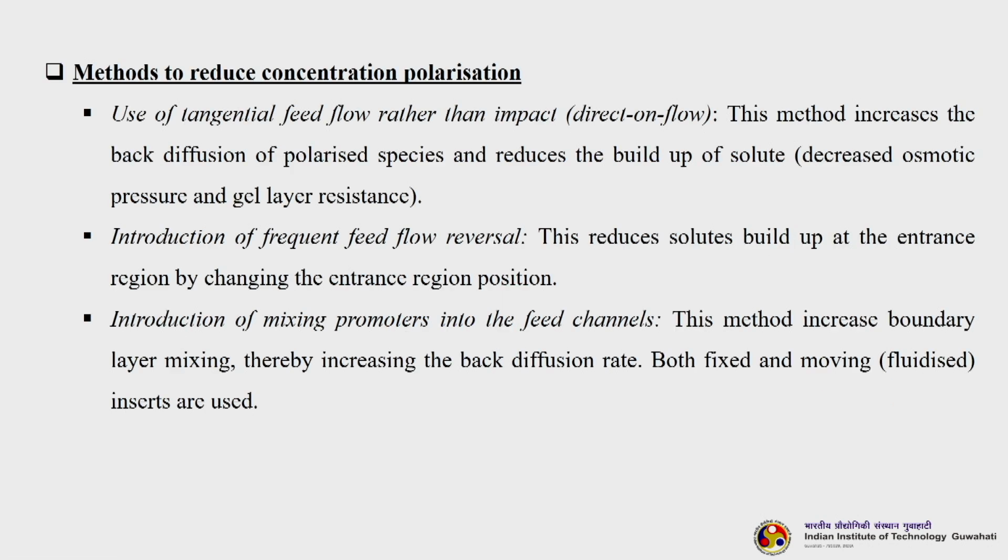Though we have discussed how to reduce concentration polarization, I will just quickly go through some of the other techniques. You can use tangential feed flow rather than impact, that is direct on flow. This method increases the back diffusion of polarized species and reduces the buildup of solute, basically decreased osmotic pressure and gel layer resistance. Another method is introduction of frequent feed flow reversal. Now, this reduces solute buildup at the entrance region by changing the entrance region position.